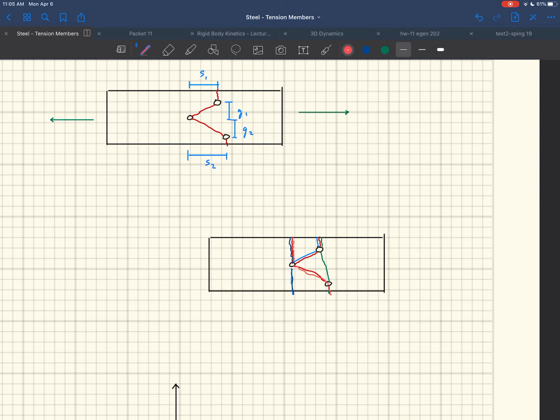You'd have to calculate the net areas for all of those cases, right? We don't know. We have no idea until you calculate. Sometimes you can apply some logic to it and go, oh, clearly if it's going to break through 2 holes, it's going to break through this, right? If you have two lined up, we know that it's going to rip through 2 holes before it rips through these 2 holes, for instance. Anyways, sometimes you can apply some logic.